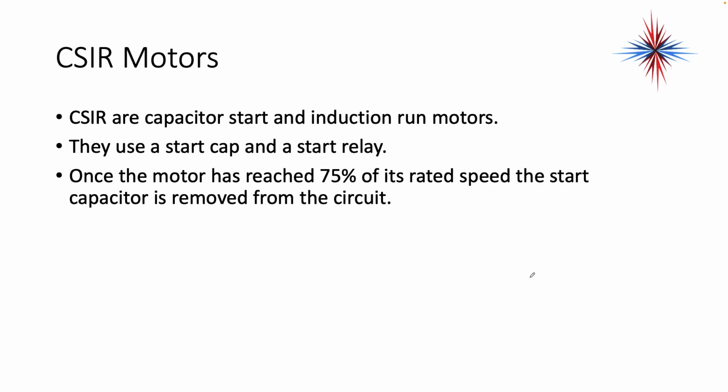CSIR motors are capacitor start induction run motors. They use a start cap and a start relay. Once the motor has reached 75% of its rated speed, the start capacitor is removed from the motor.